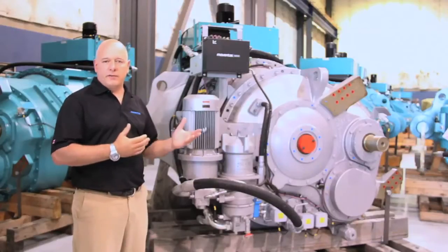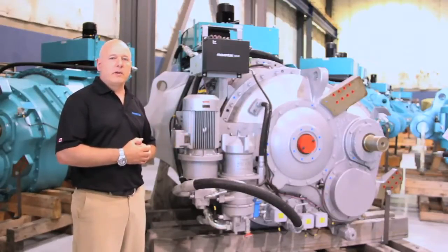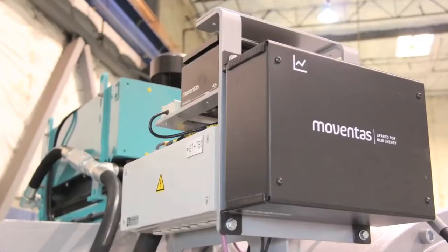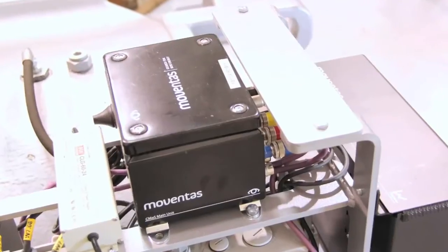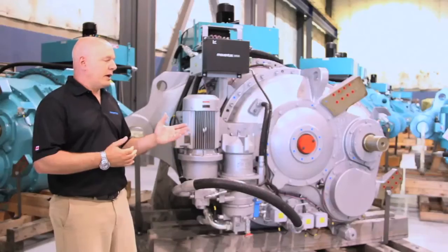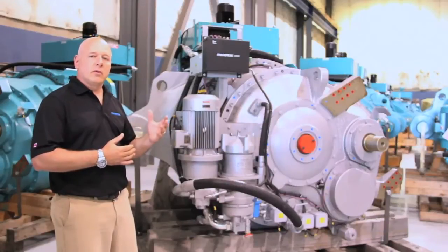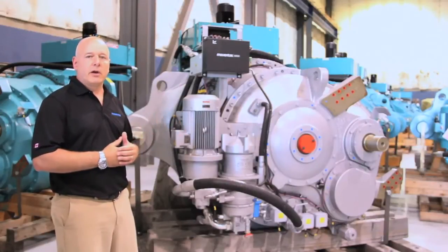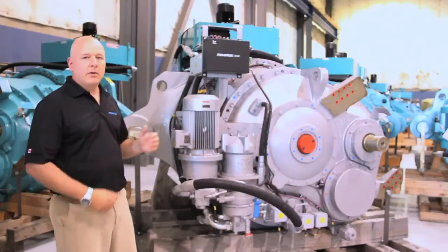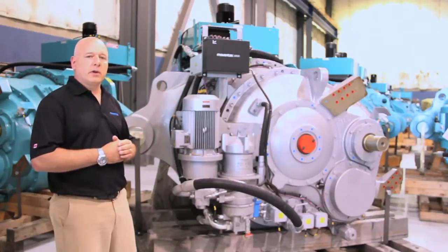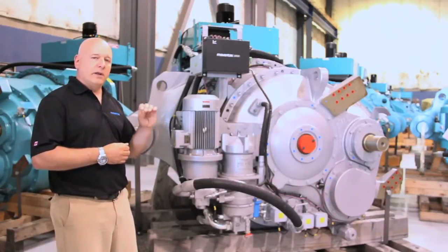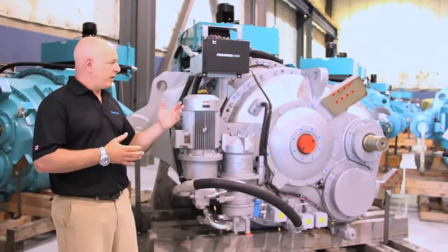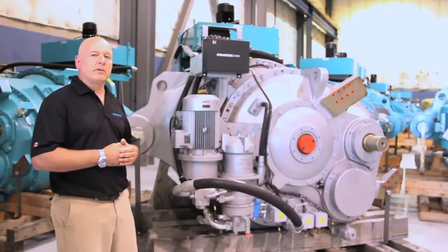We started looking at the various technologies available for this: vibration analysis, oil particle counting, and an oil chemical sensor. Vibration and particle counting were both looking at defects that were already occurring in the gearbox, whereas the chemical sensor gives us a chance to look at the condition of the oil, and if we know that the oil is declining, we can do something about that before we actually get to a failure.